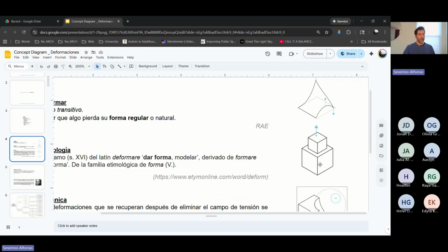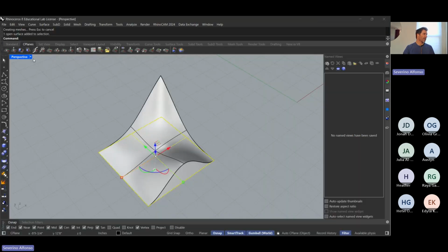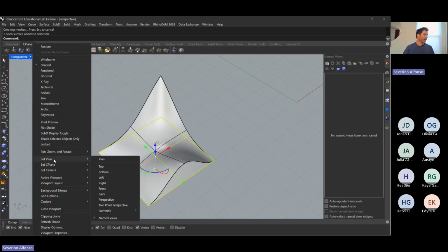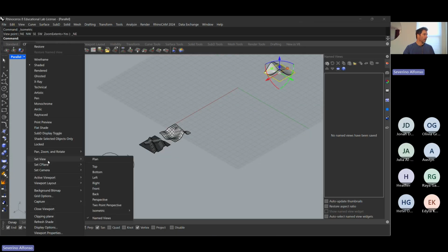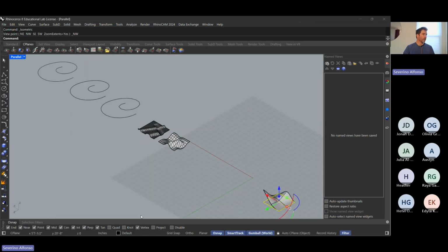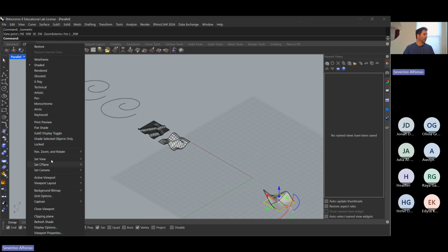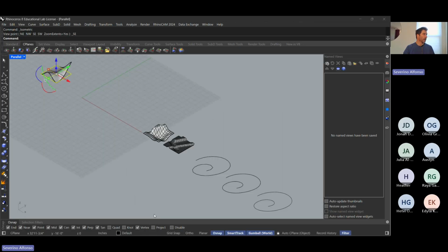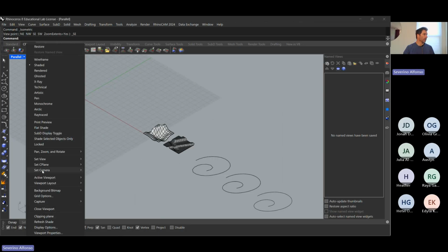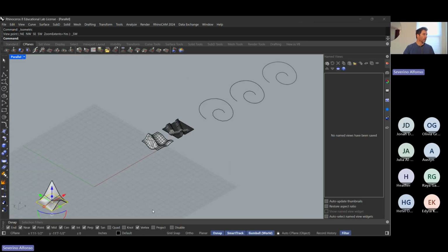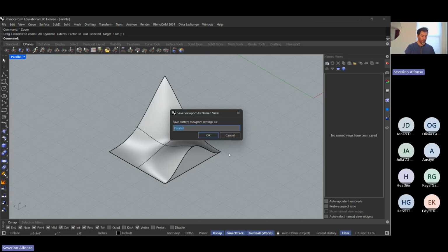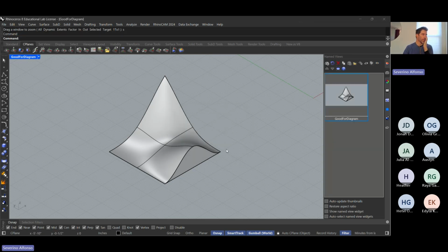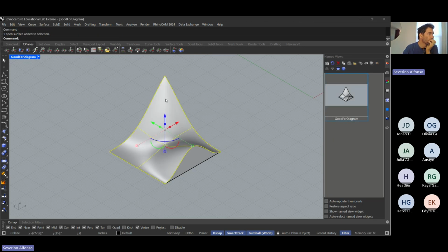What I did for all this is the same angle view. So what I think I did is just set view isometric, and I don't remember which ones. I don't think it's northeast, northwest either, until you find the one that you really like. This one, southwest. So select. You can save the view, say good for diagram. So I can always go back to this if I need to, and then you will start doing your make 2D.